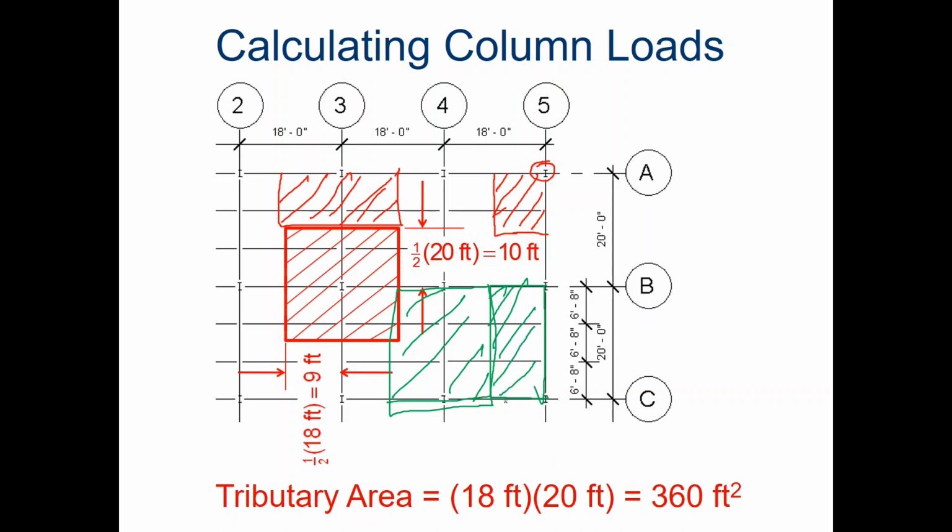All right, so it's getting a little messy, but hopefully that makes some sense. And same with these beams. The interior beams will have a full tributary area. Any of the beams that fall right on the edge here are going to have half of the tributary area.